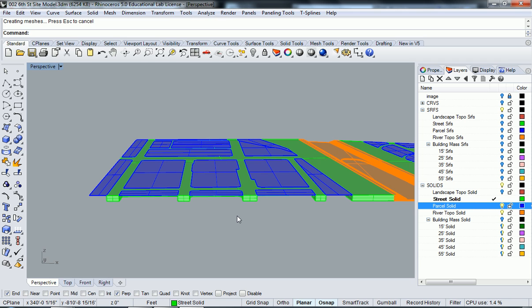It's going to allow you to scale these things similar to how you would move things, or how you would extrude something up and down. You can also take something and scale it in one direction downward. I just literally said the name of it right now, and it's called Scale1d. So let's type in Scale1d.